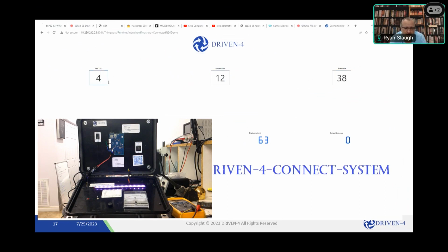The LED lighting here, the different variables from 0 to 255, determines what color you have. If all of them are 255, which you'll do here in just a second, you'll have all of them bright white. All of them are 0, of course, all is off. The main aspect here is to show just that control, especially with MQTT. Now, if we wanted to do this with the JSON structure sending back and forth, we could do that as well. MQTT is really kind of a nice focus for this type of environment.